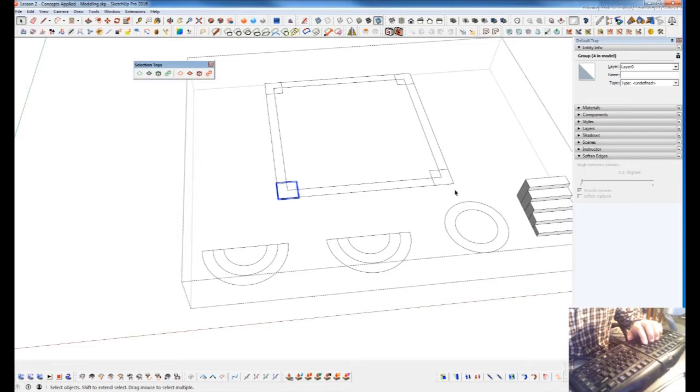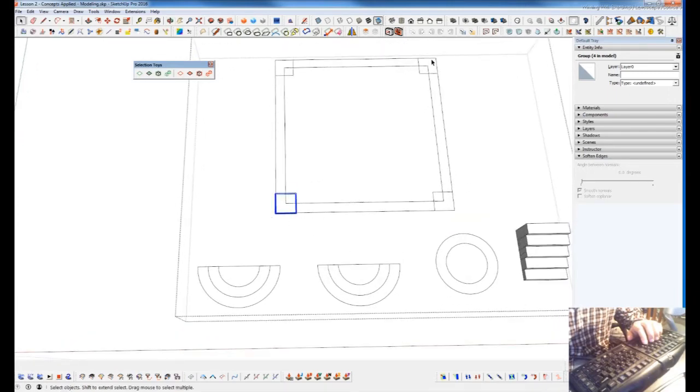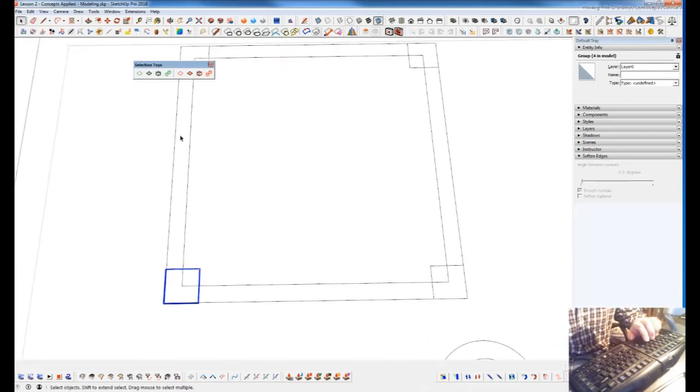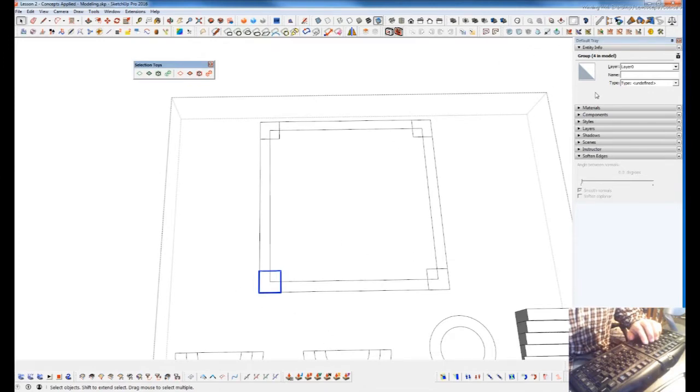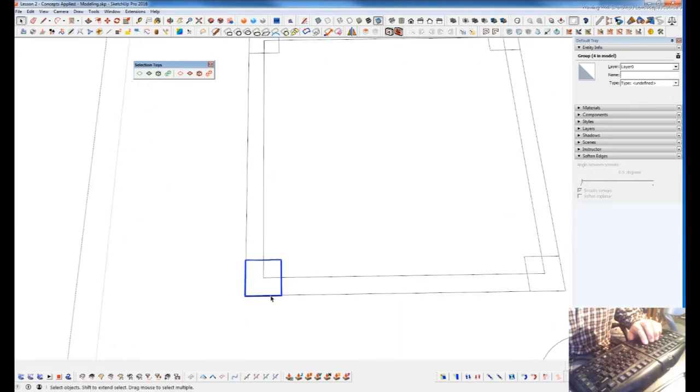So let's say I move these boxes around. The nice thing is, even though groups aren't committed to instancing like components, which is why there's a difference between the two, it's why they're so similar except for that one difference. If this were a component and I manipulated it, then all 4 would be manipulated. But groups will also retain the fact that there are other copies of groups.